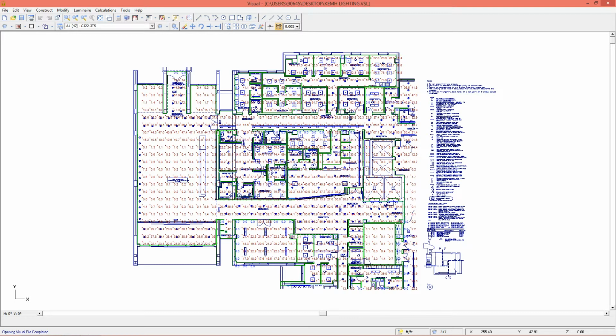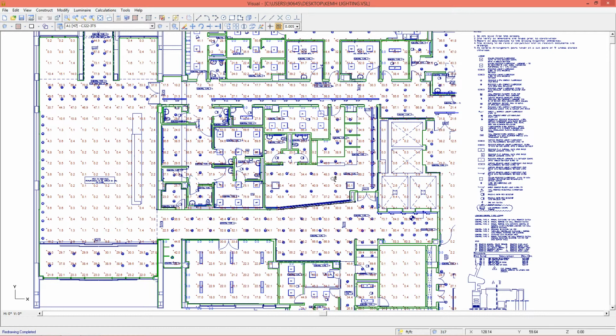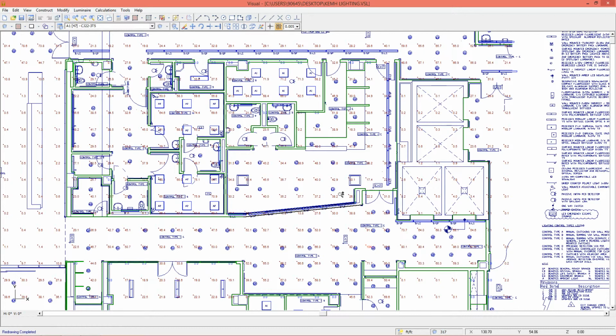Now, let's get the lighting programs to take over and do all the hard calculations. Here I've brought up a model of a hospital that I did just recently. We were required by the architect to do this for AECOM, and had to make sure that the correct reflectance, light loss factor, which is also known as a maintenance factor, and working planes were used. For reflectance, we used 80% for the ceiling, 50% for walls, and 20% for the floor. The working plane was set at 2 feet because that's the approximate working plane as was requested, and the light loss factor was set at 0.9.